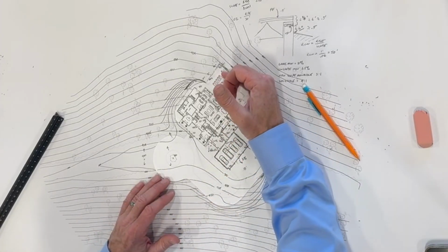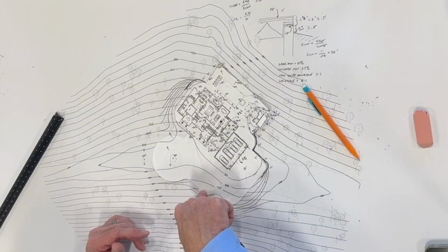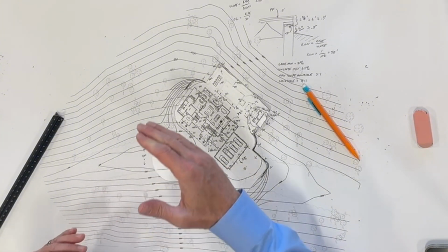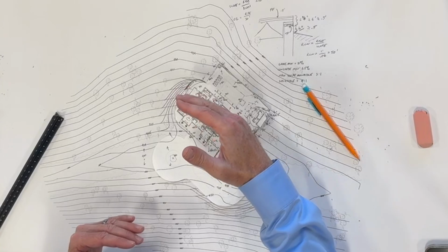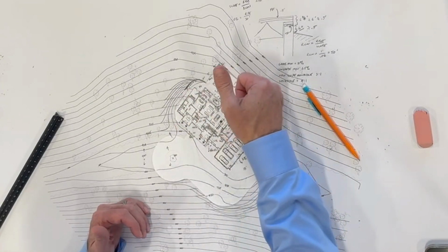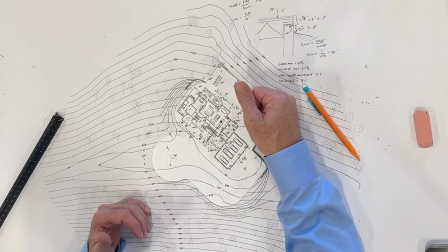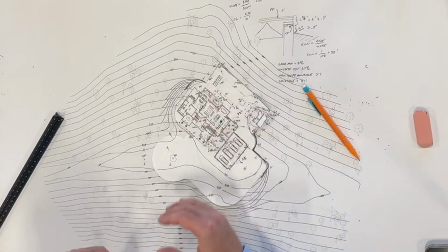There's a lot of retaining wall here. If we moved it this way, this retaining wall would get lower, but by definition, this retaining wall would get bigger. So usually the retaining walls end up being the same. It's just sometimes a 6 foot and a 6 foot retaining wall might be better than no retaining wall and an 11-foot retaining wall, right? If you kind of want to do it.